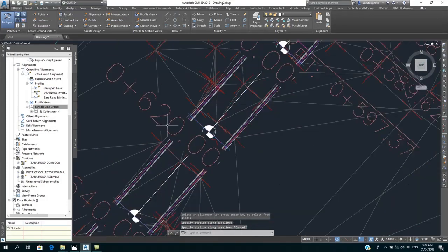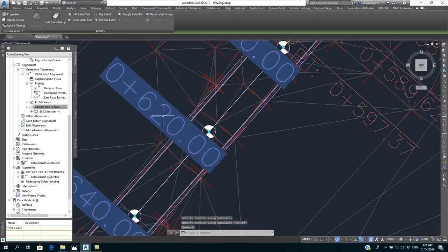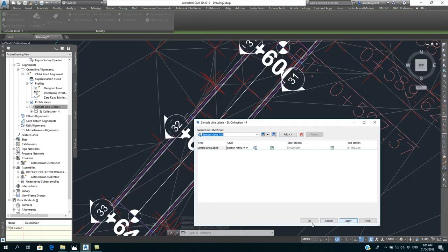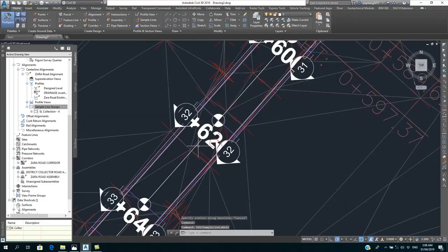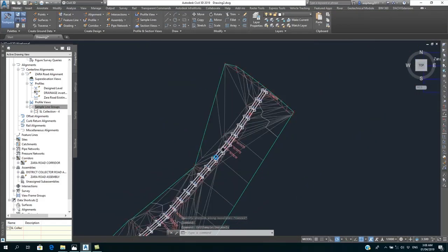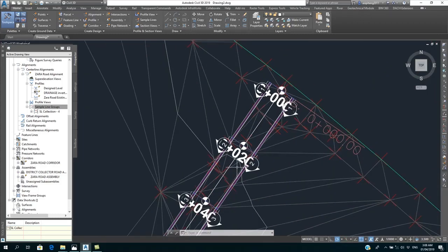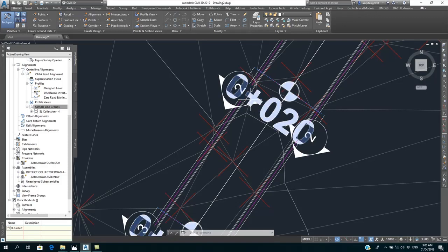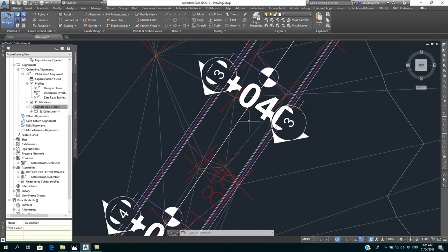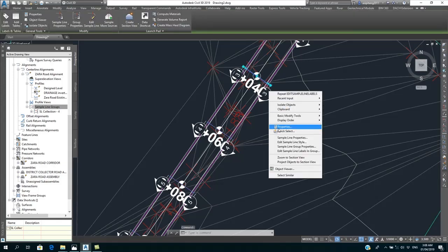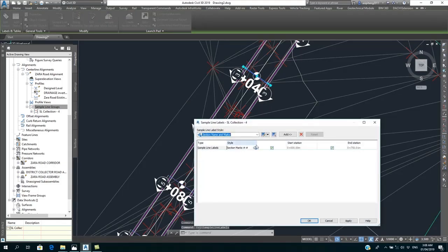Then here at the same time, at the interval I've shown, I can edit the labels. I've already defined everything. They do the labels. I remove this style. I have my own design which has been done. For detailing, the cut section you can see at this interval. So I have this information now showing and cutting in at these intervals. So I can remove this, so it doesn't obstruct my information. You can see this is a line, I can edit this information. I can even remove it. So here now I can click on this, not show the lines again, or the sample line groups. I can remove this, not showing information.